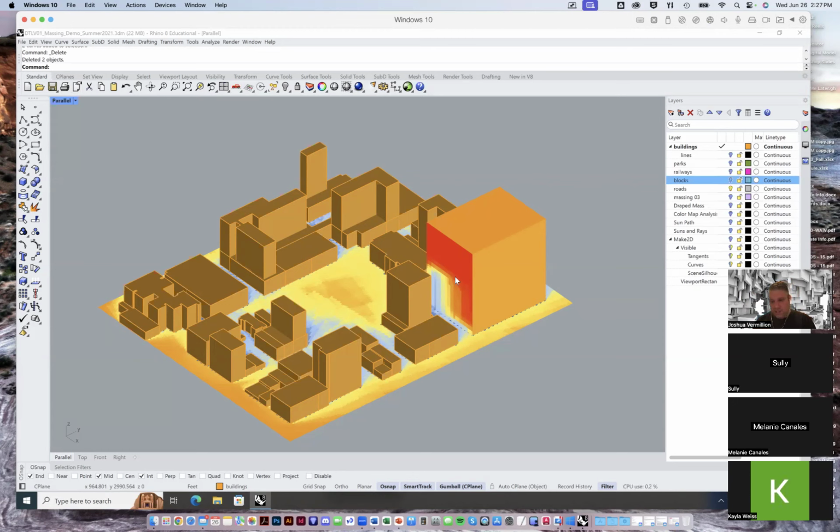So I would say there's something interesting about doing some shadow studies in Revit at key times of the year and day. And it's a lot easier to bring out those isometrics. It's already set up to just be an axon, and you can just bring out the image. Okay. So I recommend doing your sun studies in Revit anyway.